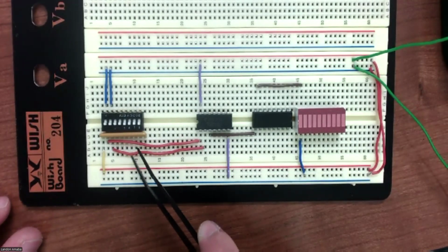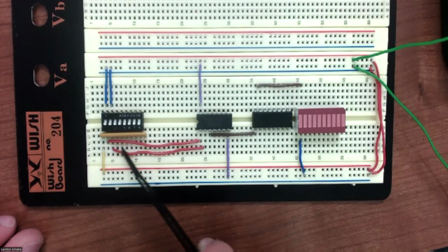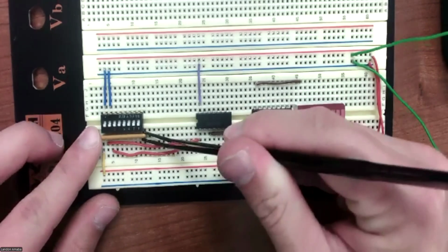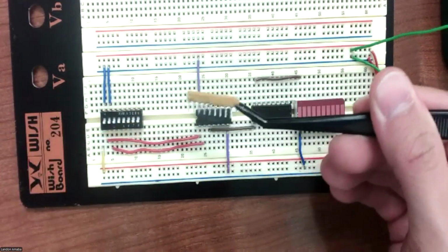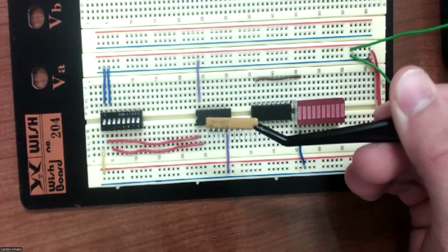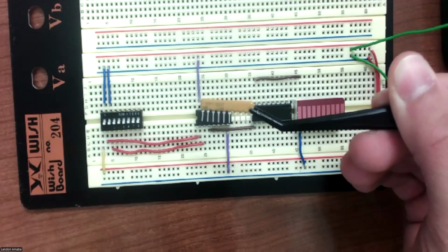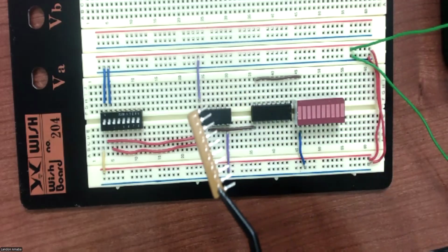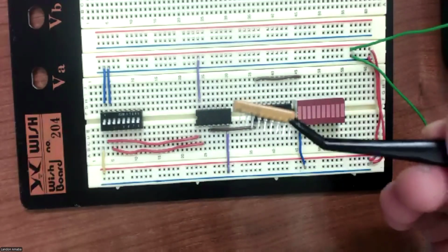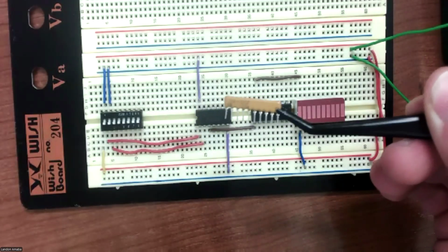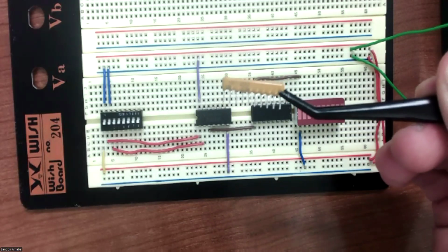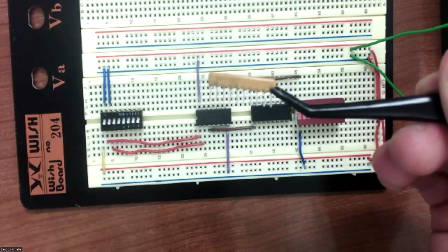When you wire up this SIP resistor, there's an important thing to note. I'll go ahead and take it out of the breadboard. With this resistor, you can see one side has some black text, and on the other side there's nothing. On the side with black text, you'll see a small dot on the leftmost lead. This indicates where your power is going to go.